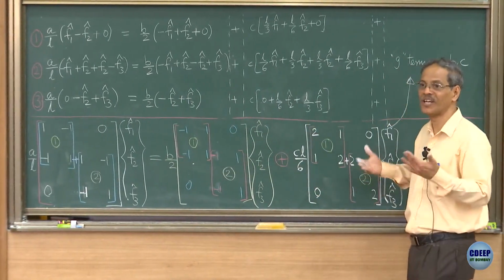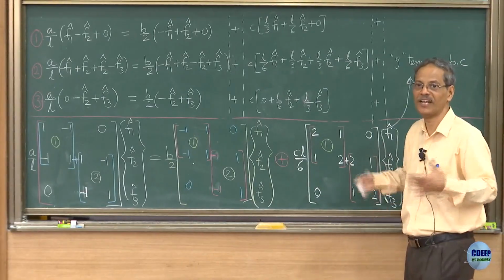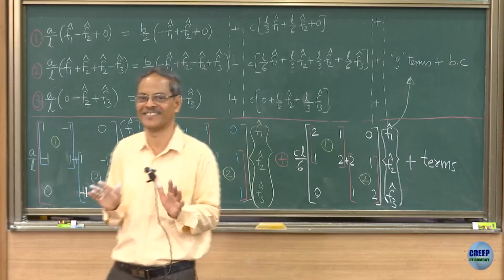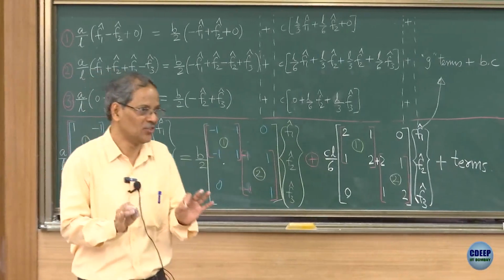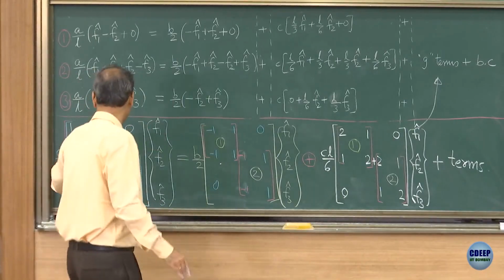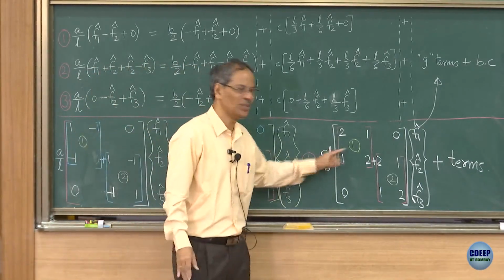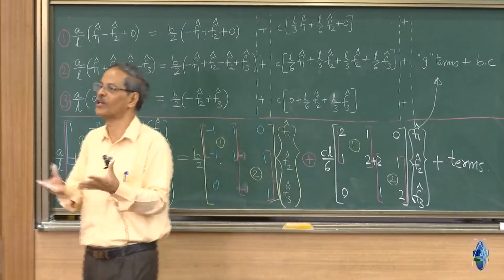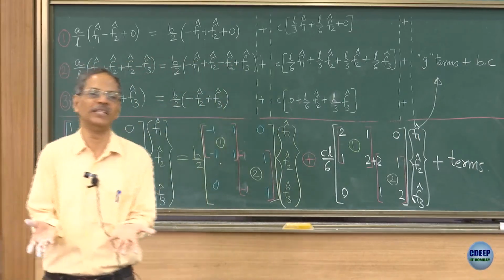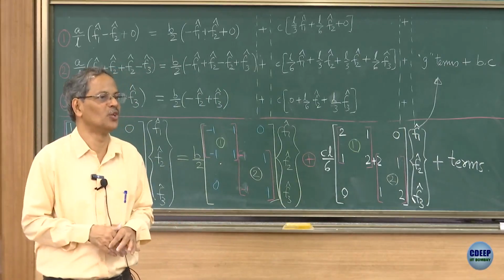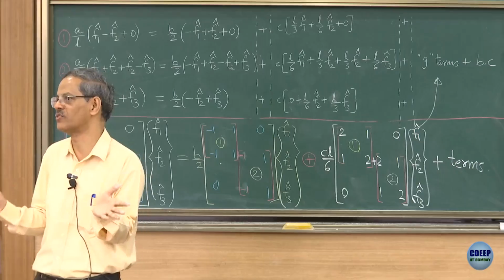If I were to take the third element, it will be again repeating, 200 elements, 200,000 elements. It does not matter. What would change? Of course, for convenience now, I have taken L to be the same. But I can write it in a small computer program. Whatever be the length, it can take that as input data from you and compute the element level matrices.